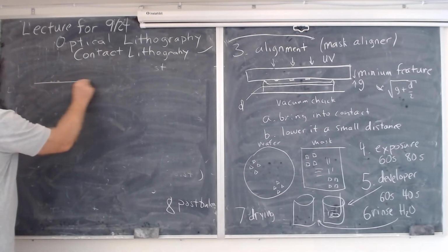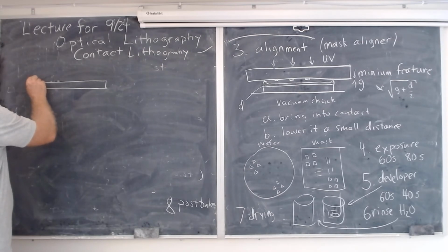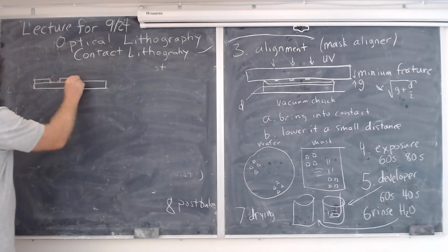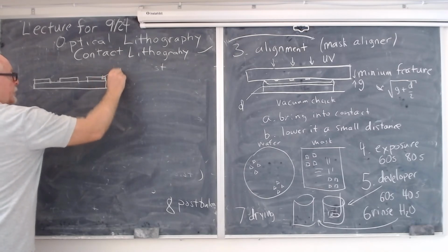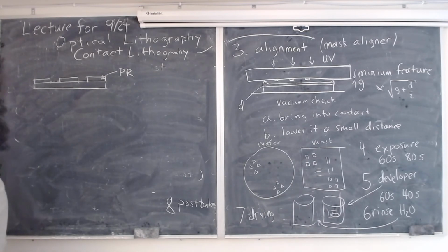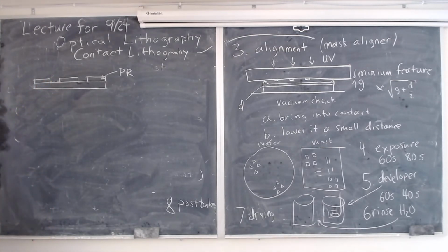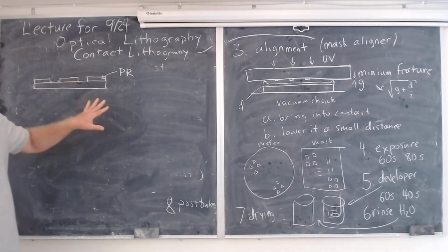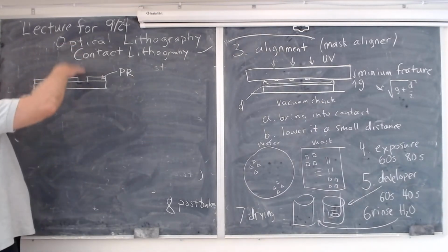So here you are with your wafer now. All right, and you say you have some features in your photoresist. So that's photoresist. And through this whole process, you've created openings in the photoresist where you want them to be for whatever step you're performing next. And if that step is, for example, liftoff, you pretty much are done there. You put it in the evaporator, you deposit metal.